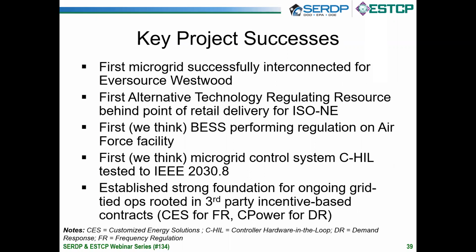For microgrids, especially military microgrids, this becomes kind of impractical because a lot of the time you can't site your equipment at that point where you're being metered by the utility, or you're using existing equipment where you have to move it and electrically connect it differently. It just becomes impractical and unaffordable to do. Moreover, if you want to use the asset as part of a microgrid, you really want it connected within the microgrid, not directly to the utility, because otherwise it's not going to be able to support that microgrid.